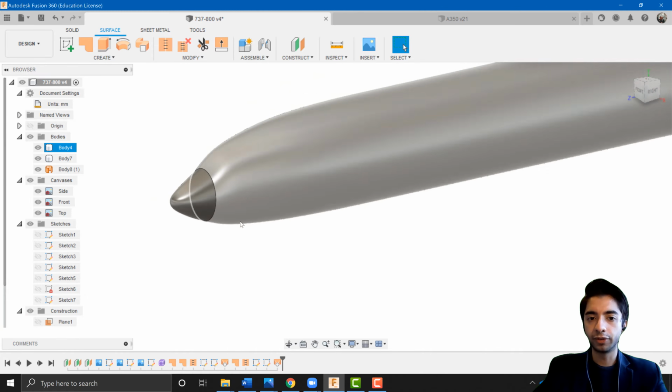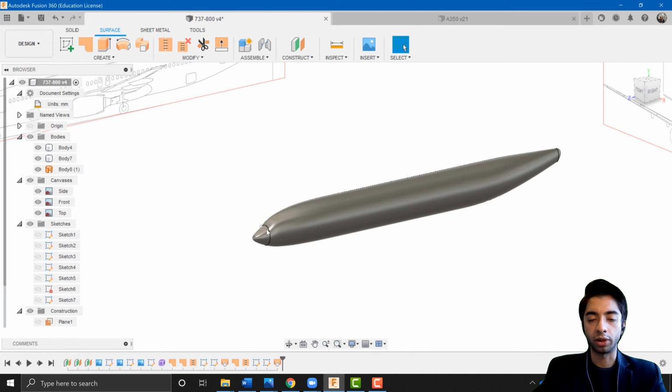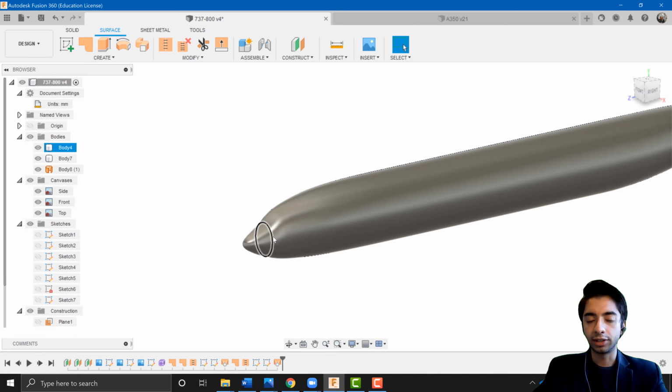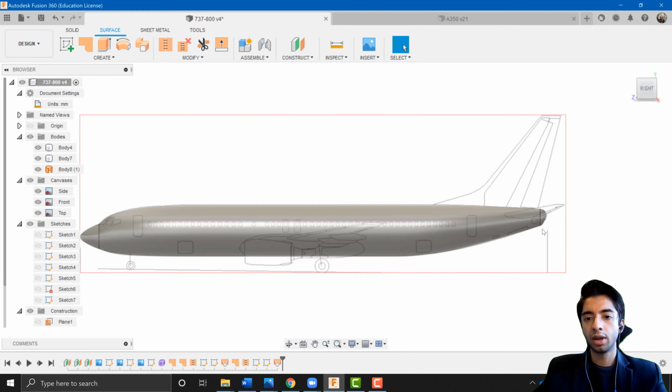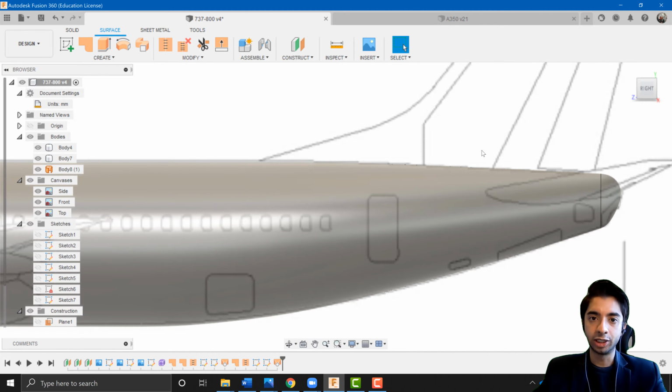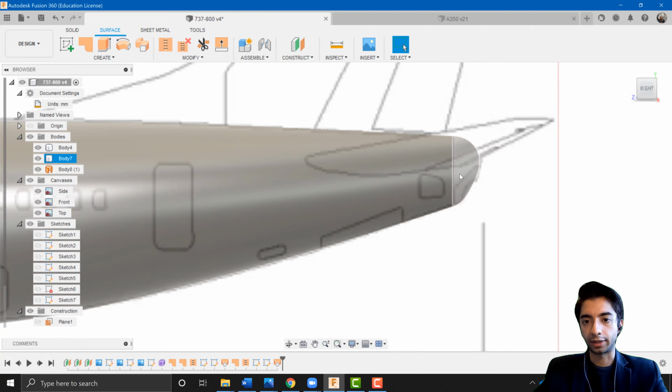Now, at this point, some of you may encounter some issues while you were trying to do the loft. In that case, you want to probably troubleshoot. And the way to troubleshoot that error is you want to ensure that when you made the T-splines, they were vertical. The second thing you want to ensure is that the side curve you create should not have a length that is too much longer than the width of the aircraft. The third thing you want to try and do is ensure that when you are pressing the loft tool, nothing else is selected apart from the 3 surfaces.